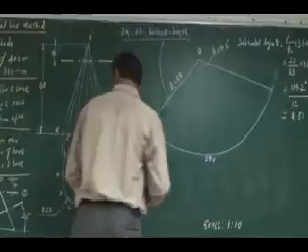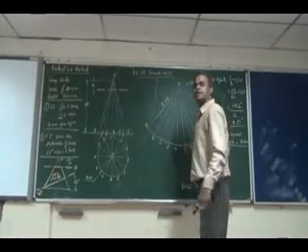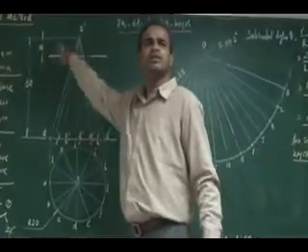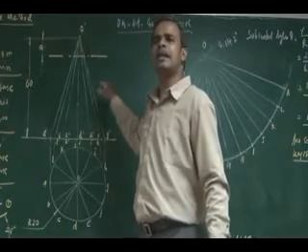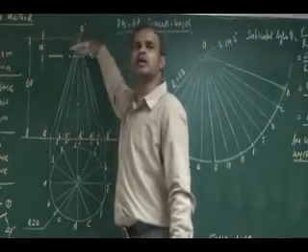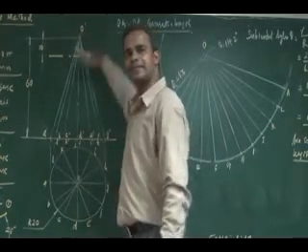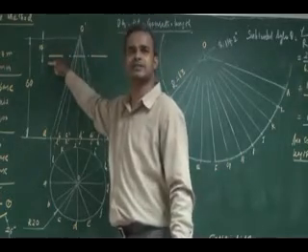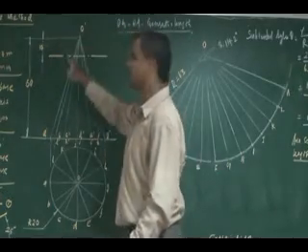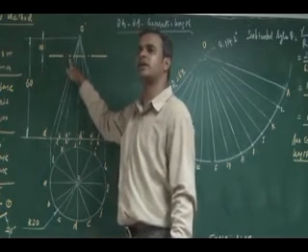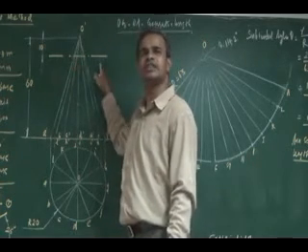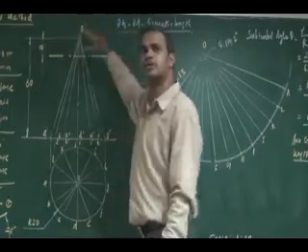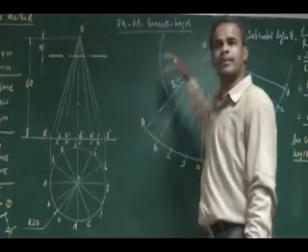See here, the circumference points, the circumference locations. Listen. The first cutting plane, to form the lamp shape, cuts parallel to the base and perpendicular to the axis, something like this, 10 mm away from the apex. Once it cuts, I need not show the cutting point. It cuts all 12 generators, so I have to mark 12 cutting points. For these 12 cutting points, the length will be the same from the apex.